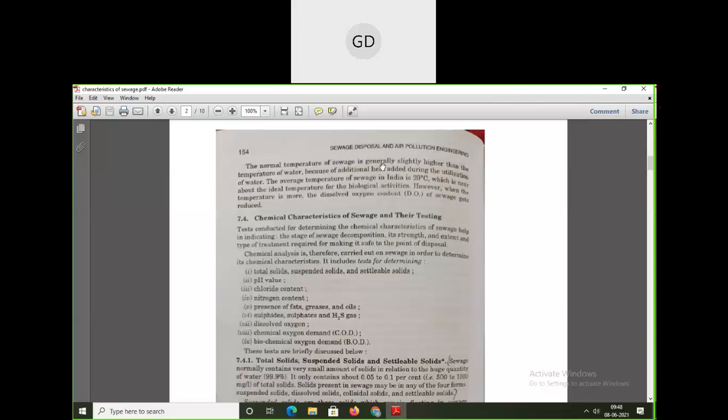This was the formula, which has already been explained to you. TON is equal to (Vs plus Vd) by Vs. What is Vs? Vs is the volume of the sewage, how much sample you are taking. And Vd is the distilled water you keep adding to the sample, making it odorless finally. So this whole thing is your formula for TON. If a numerical comes, I have already shown you, so you can refer to that video.